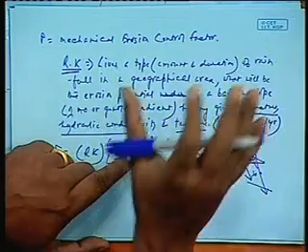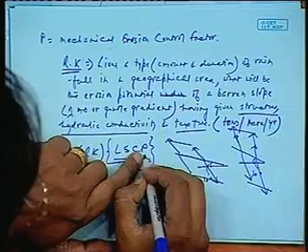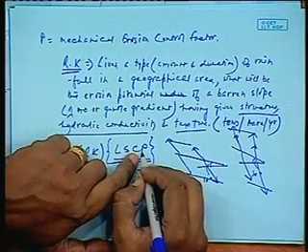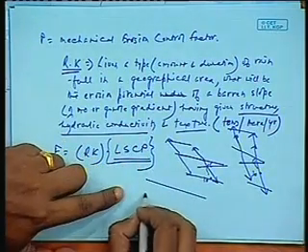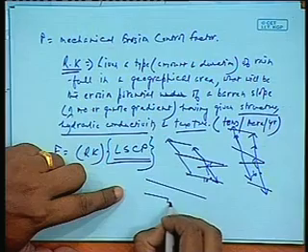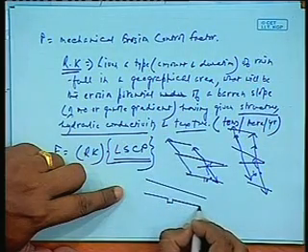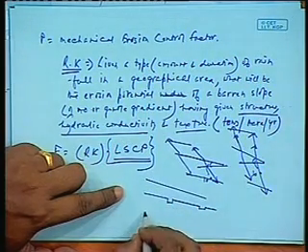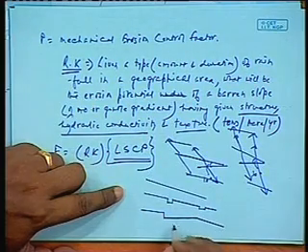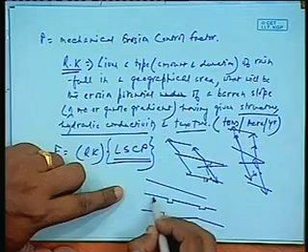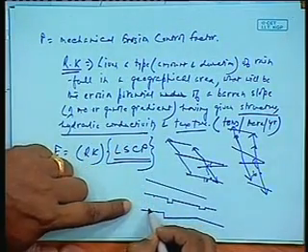So we are using C as a factor which, if applicable on the slope, would bring down the quantity of erosion. And then finally there is P. P is the mechanical soil erosion control. So understandably, if there is a slope having a diversion ditch or a terrace, in such cases the erosion would be reduced, isn't it.